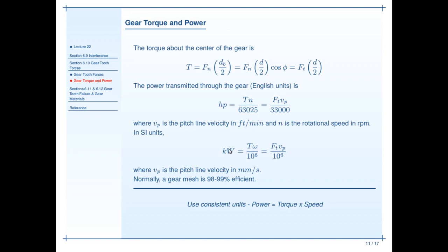In general, when you're doing this kind of calculation, I do suggest that if you have English units, it's worthwhile translating them into SI units, performing your calculations in SI units so that you have nice, consistent, easy to understand units, and then translating back to imperial. Therefore, one of the worthwhile imperial unit conversions to always remember is that 1 horsepower is equal to 746 watts.